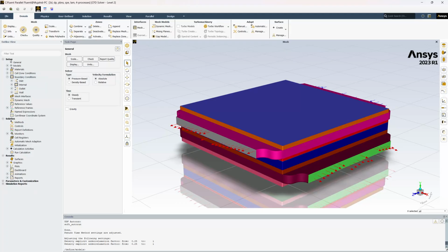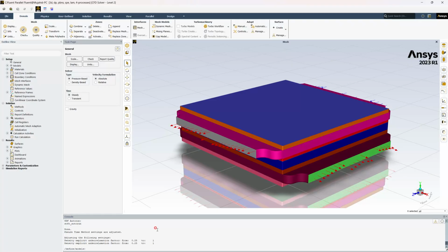Now we have defined all the things necessary for the simulation, but to get a proper simulation we need to define the report definitions. We already previously set all the report definitions, so we can directly import them. We've already discussed in detail how to set the report definitions in the previous chapters. These are the same expressions and report definitions, but only the area selections are changed.